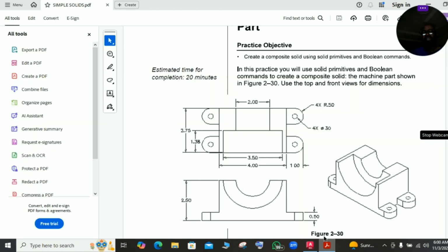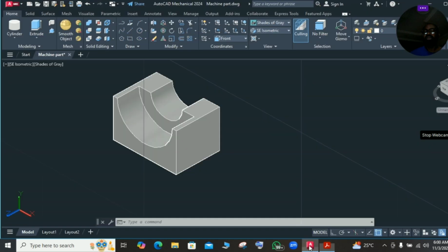The next stage is to draw these 4 legs with this dimension. Okay, this is the height, 0.5. And it has a radius, supposed to be a boss of 1 by 1, having a height of 0.5. So the radius of this curve is 0.5. Okay, so I can decide now to come and use boss command,